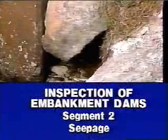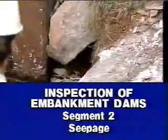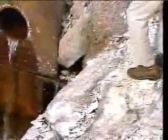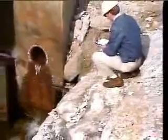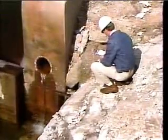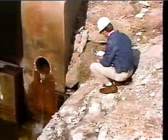Welcome back. Obviously, when we're inspecting the slopes and crest of the dam, we're looking for deficiencies. One major area of concern, as you've just read, is seepage. Seepage is not always a problem. It becomes a concern when it erodes embankment or foundation materials, or when it creates excessive pressure in the dam or foundation. We're especially concerned with uncontrolled seepage, seepage which appears for the first time, or seepage which increases suddenly.